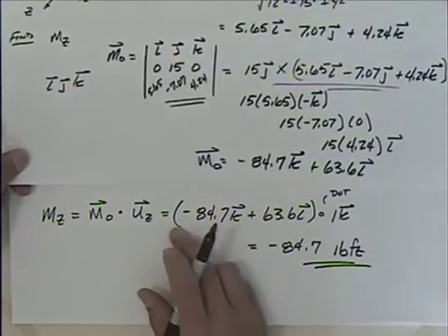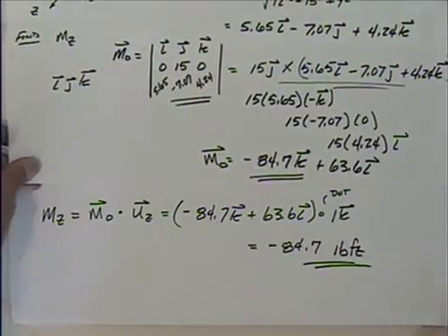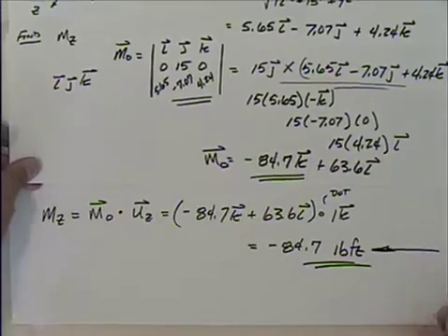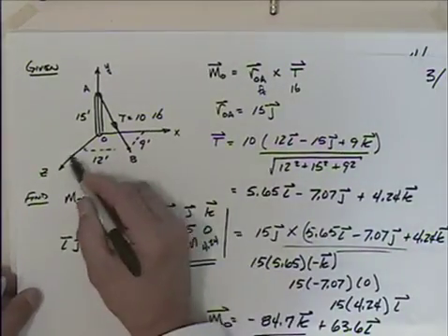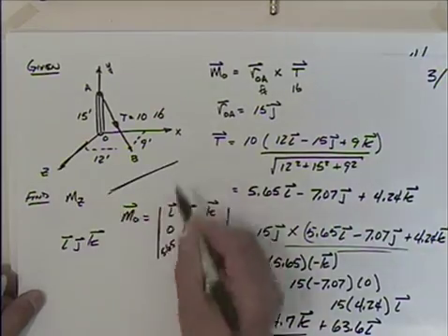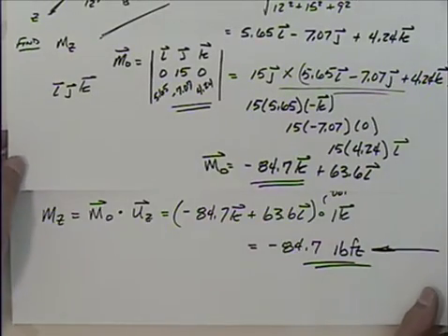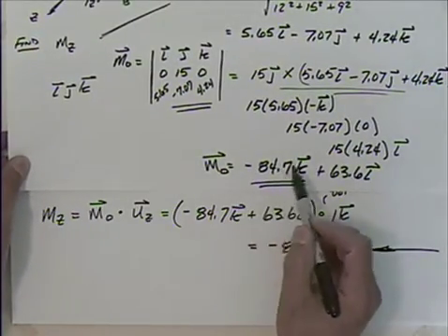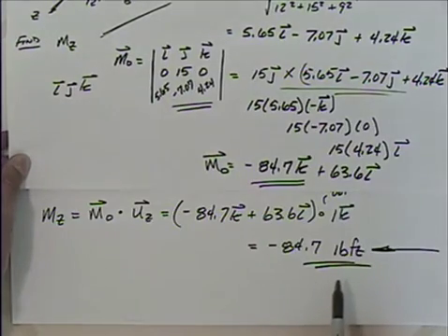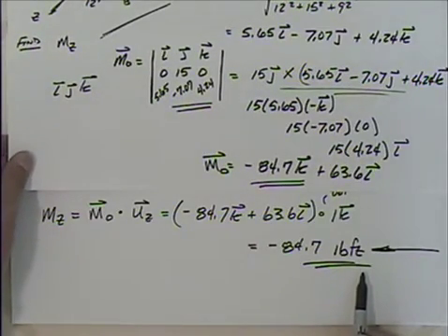And with this triple scalar here, I kind of made a big deal. Most people will just look at that and say, well, hey, that's the Z component right there, and that matches our answer. Now, if they wanted to know it about some line somewhere, instead of on the Z axis here, then you'd have to find the unit vector for that, and probably this would be a bit more useful. So pretty straightforward. You go ahead and find the moment about a point, and then dot it with the unit vector for the direction that you're trying to find the component of.